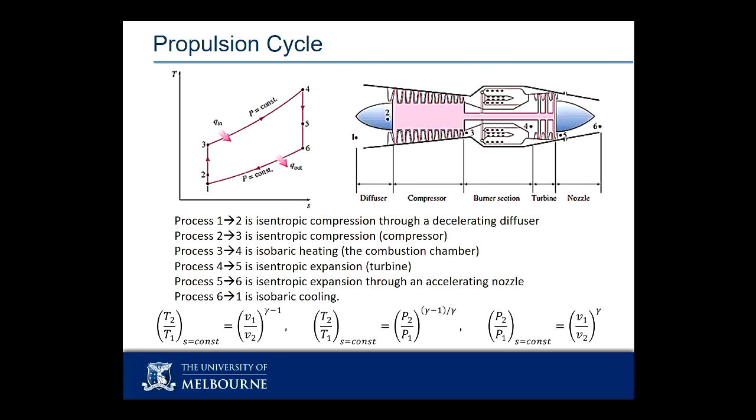They work by taking your isentropic relationships, which we built up last lecture, as well as your ideal gas, as well as your PV to the gamma, put them all together, and you end up with the isentropic ideal gas relationships. One connects temperature to specific volume, one connects temperature to pressure, and then you can, of course, connect pressure to specific volume.